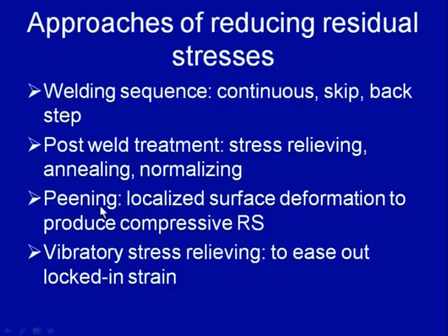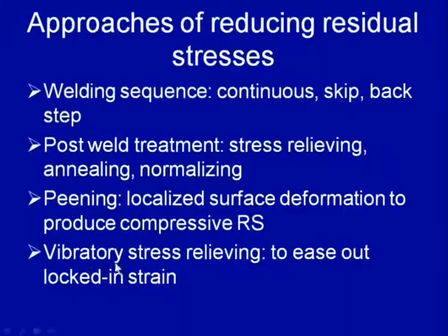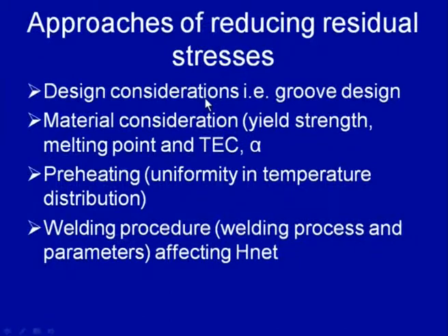Then use of the mechanical force to relieve the residual stress is also used, using shot peening, where the localized surface deformation is used to produce compressive residual stresses and relieve the locked-in tensile strain. Then in mechanical methods, we have vibratory stresses, where vibratory forces are applied to the welded joint or the component in which the residual stresses are present to ease out the locked-in strain.